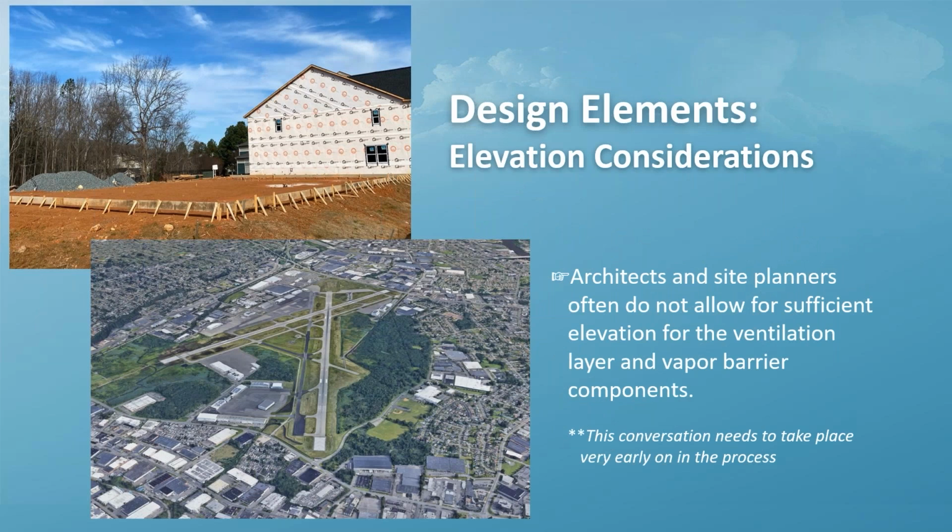Elevations are critical. Site elevation is really determined by the elevation of the existing ground, the thickness of your stone plenum, your vapor barrier, and your DGA level. Now, I'm showing you a slide here on the lower part of the screen. This is a large airport basin in New Jersey where we did well over 1 million square feet of designs for several different buildings. And the goal of this particular developer was to have everything passive.